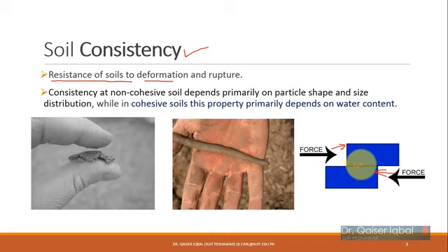Where there is a contact, there will be resistance, and if this resistance is greater, then it will take a lot of shear force to slide these two boxes across each other. But if the resistance over here is small, then it will probably take less force for you to slide these boxes past each other. So the resistance available at this surface is basically the shearing resistance.